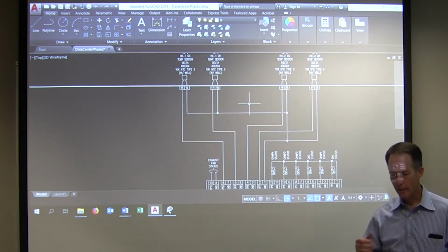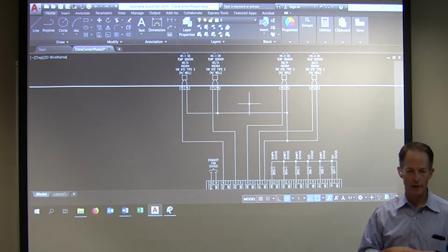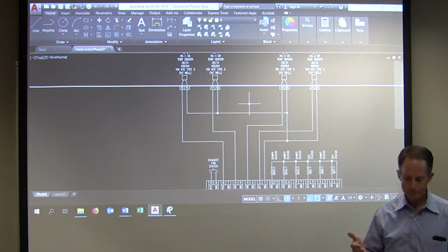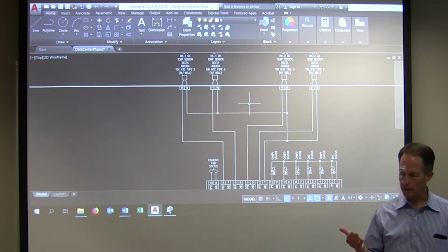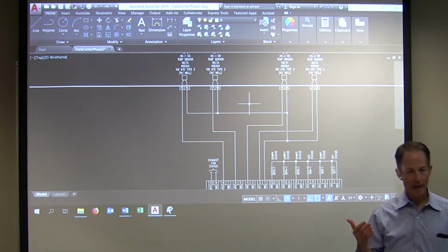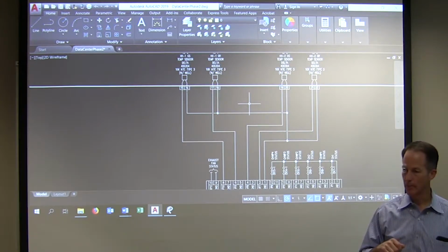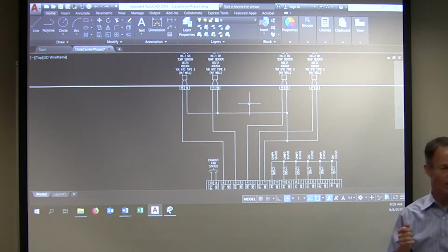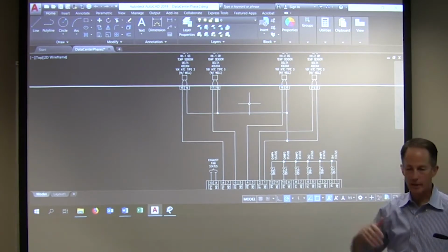And so the older style where it was a screw down, those aren't nearly as good. They can come loose over time. Somebody once told me that amusement parks, by code, have to use spring-loaded terminals. They can no longer use screw-down terminals, because if you lose a wire on a roller coaster and something doesn't work right, that's not a good day, right?